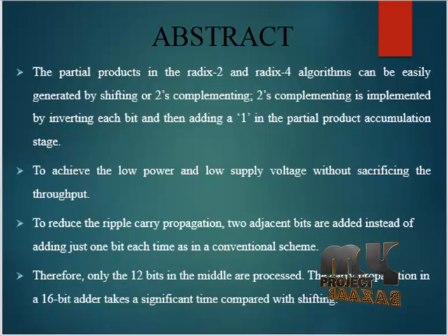The selection of partial products as input to the Wallace tree is controlled by the partial product generator. The multiplier encoder determines the input signals to the partial product generator. The decoding process occurs in the Radix-8 algorithm, and the corresponding adder functions are calculated. The AND gate selects the partial product and performs the shift operations, while the XOR gate completes the inversions for the negative multiples of the multiplicand.